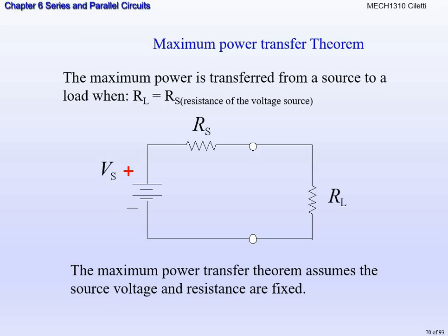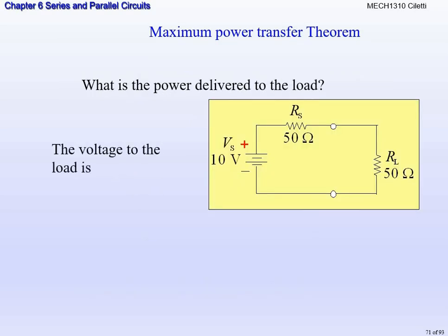That's why when you buy speakers and they have 8 ohm impedance, the 8 ohms that's coming out of your car stereo has to match the 8 ohms on the speaker that you plug into, so that you can get the maximum power transfer. If your stereo is 8 ohms and your speakers are 4 ohms, you're not going to get maximum power out of your speakers. So hopefully that relates for you guys.